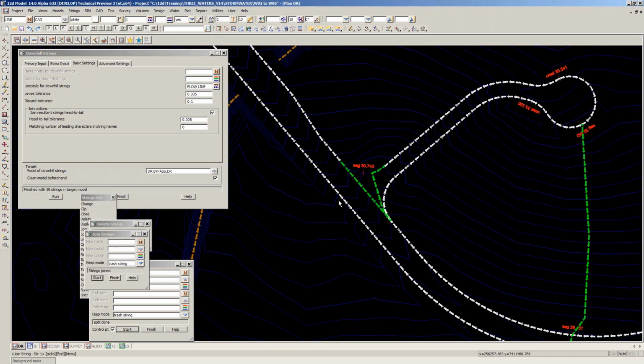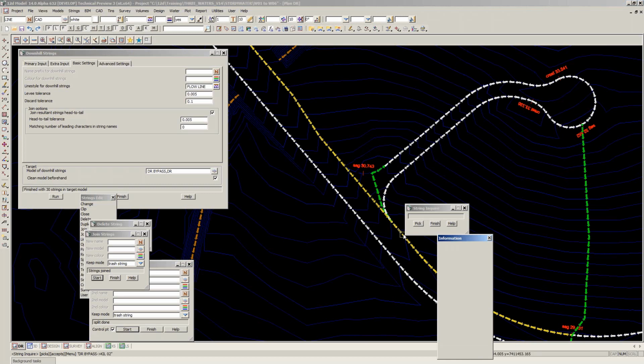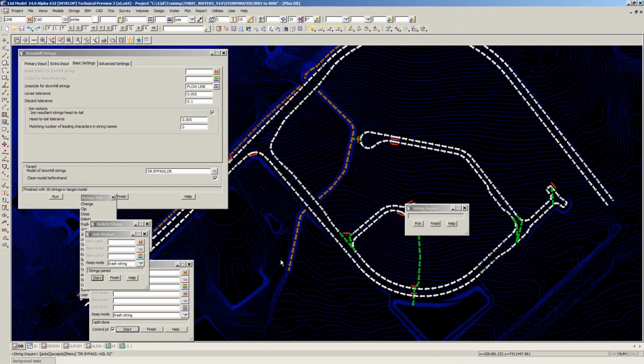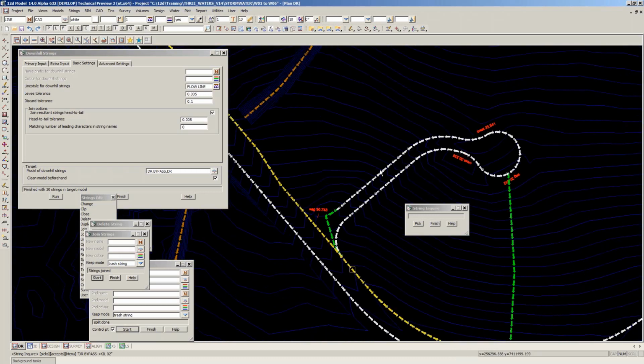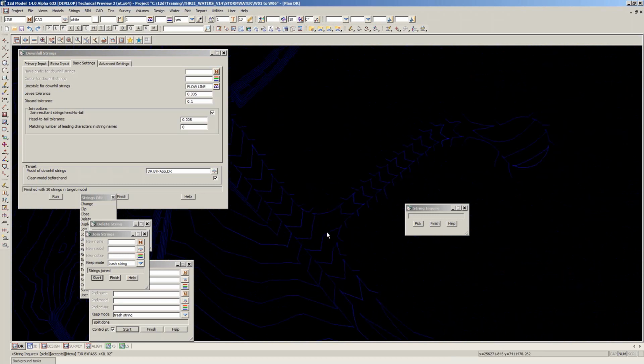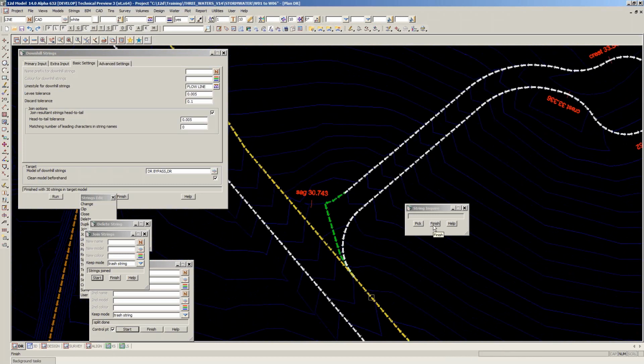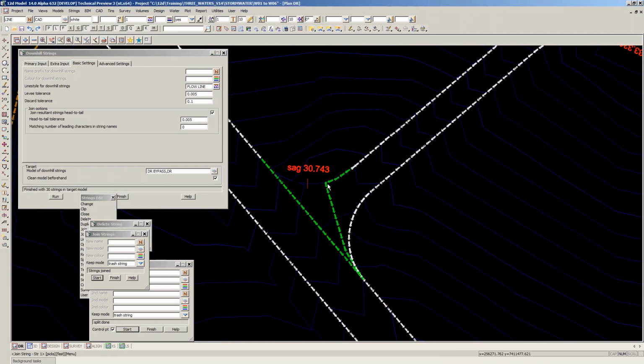And I now have one nice continuous bypass string starting all the way from this crest all the way flowing down and around the hill and down to the sag there. And these 2 side roads, well, the 2 paths on the side road there, they will end up going to the same point. And another point to notice here is this one here, where the road gets very flat there and the water is really just sheeting across the road there. There's no channel to form, so don't worry too much about precisely how the water gets to this point.